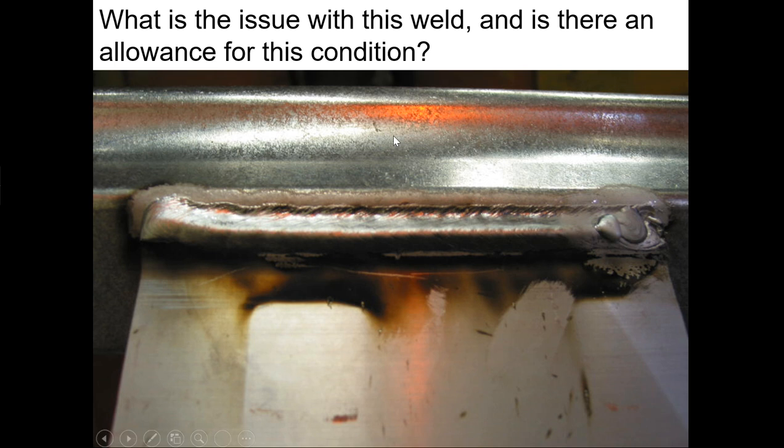Not only have we created a point where the base metal is compromised, this particular one is a weld with excessive reinforcement. So that means there's a lot of extra stress on it. And it's hollowed right out and thinned the base metal. We've lost structural integrity because it's so thinned out. The weld is typically off location. Now, what's caused this is not clear.